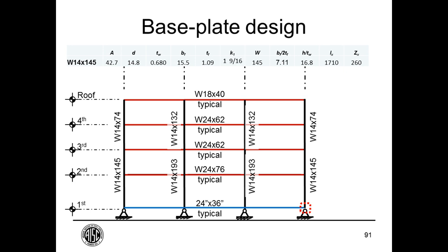But in some cases, perhaps the foundation system is so stiff that its flexibility doesn't really need to be taken into account. But for many foundation systems, there will be some flexibility, and that flexibility will contribute to the drift of the first story. And so at least that should be considered in determining whether to model it as fully rigid or select some reasonable rotational spring for that support condition.